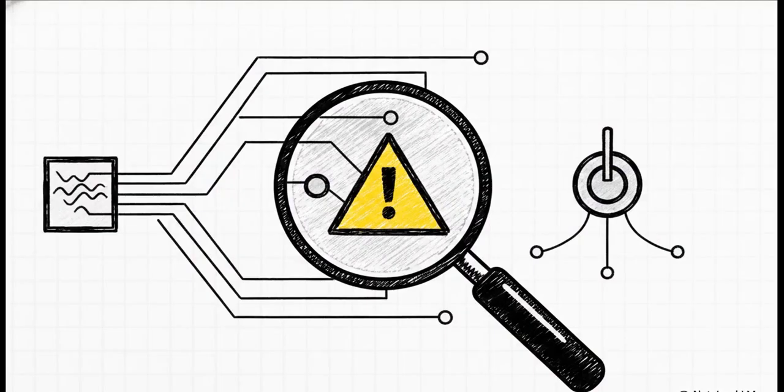Interviewers are going to aggressively hunt for your blind spots in practical design safety. They'll want to see if you know how to avoid accidental latch inferences, which can totally ruin a chip, by the way, or if you genuinely understand what unknown or high impedance logic values will do to a live circuit. They're also going to expect baseline verification knowledge, so expect them to probe your grasp of test bench architecture and basic assertions just to prove your design behaves the way you say it does.